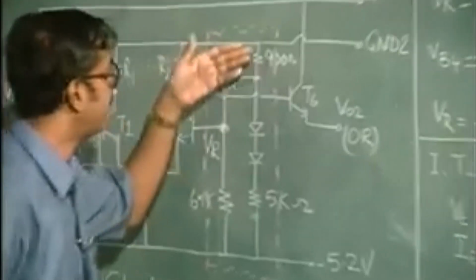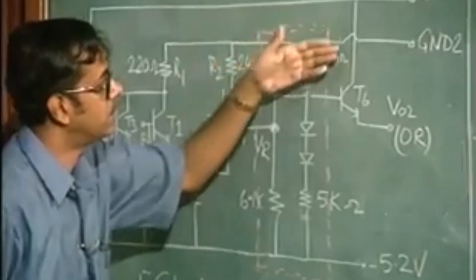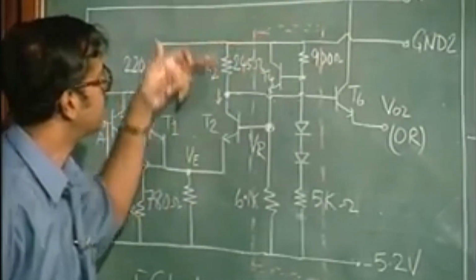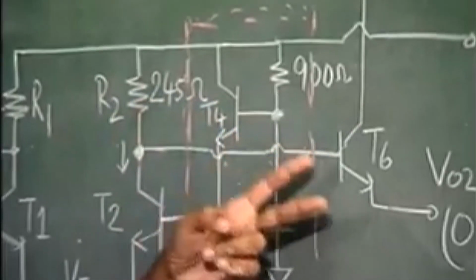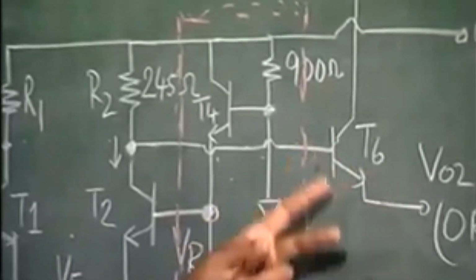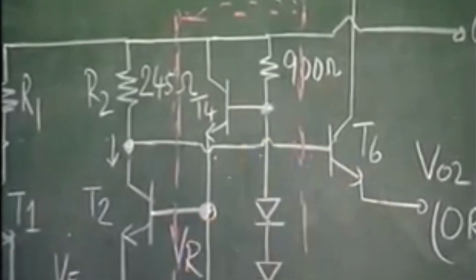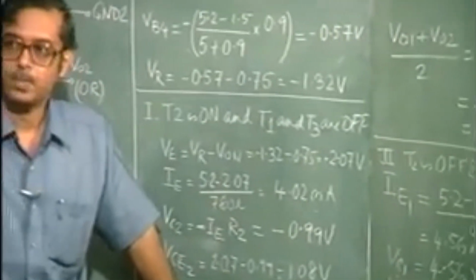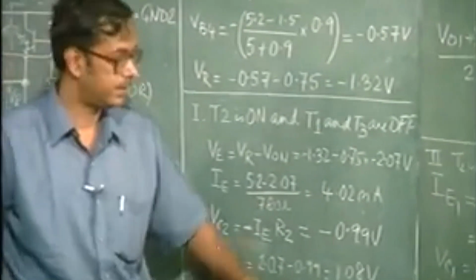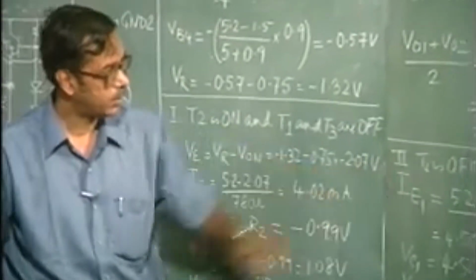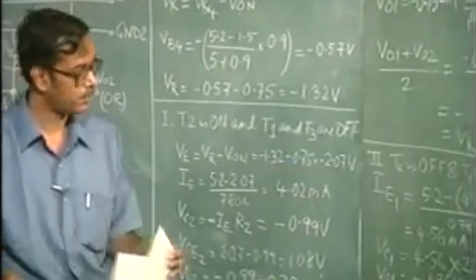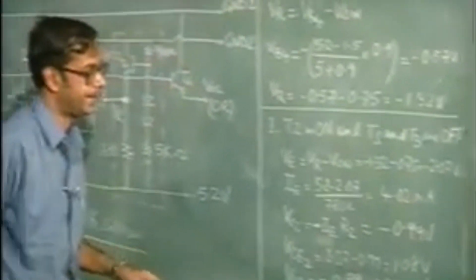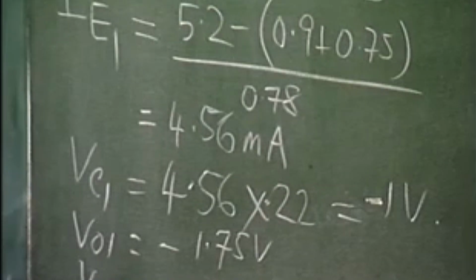Because in this case again there is no current flowing in the other branch here, this drop is 0, and the output is going to be this level, and again depending on the load current, you get the output. So, we assume that this is the voltage. Basically you see that in both cases this is true. So, the output voltages vary from minus 0.9 to around minus 1.7475 volts.